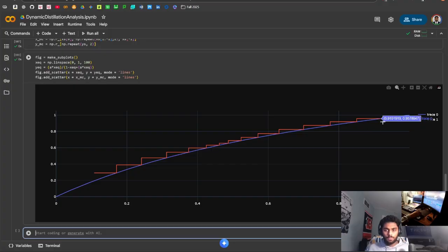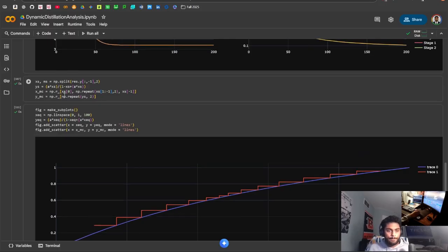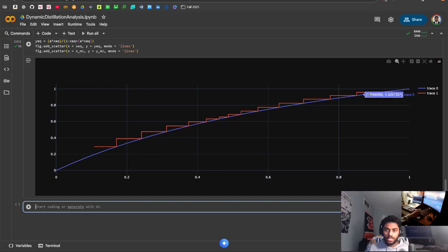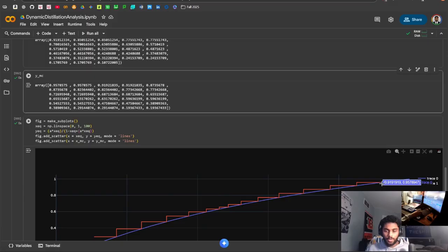Oh, that doesn't seem exactly right. Because this staircase should be under our equilibrium line and then bounded by our x equals y line. So if we analyze back this array, we see that we should have agreement between these first two data points. What ended up happening, though, is we started going over prematurely when we should be going down and then over.